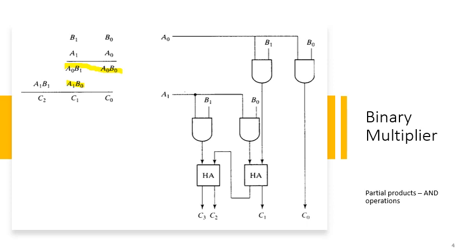Let us see an example of a multiplication, and then we'll run this example on our given circuit. For example, we have B1 equals 1, B0 equals 1, A1 is 1 and A0 is 1. If you multiply these two numbers, first this 1 is multiplied with this whole number, then for the next partial product, this 1 is multiplied with this number.